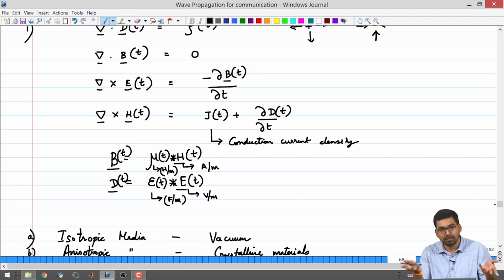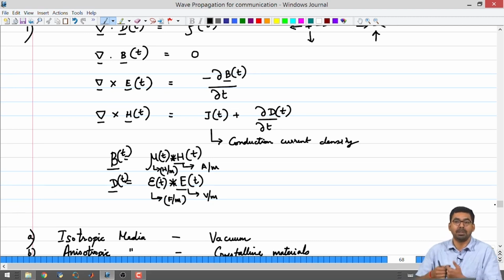Same way for the bone. Okay. In the visible it could have some permittivity and permeability, but in the X-ray region it has a different permittivity and permeability. Right. So differences in properties with respect to frequency are very useful. Okay. But they make the math a little bit more difficult, but in the majority of cases in this course we will be considering frequency independent isotropic media, because that's the simplest for us to understand all the phenomena. Slowly we will introduce some anisotropy, and we will also introduce some frequency dependence.